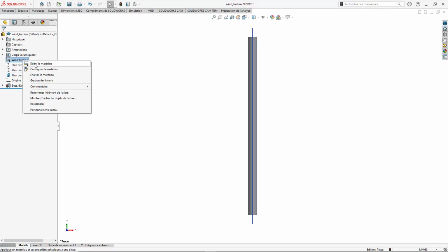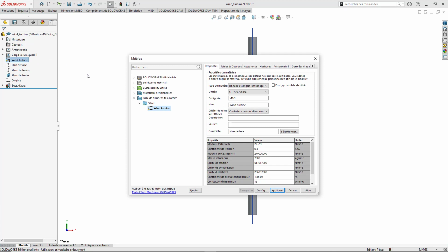We can also have a look at the parameters corresponding to the material that is used for the tower of the wind turbine. We can see that it's related to steel. Here we have indeed Young's modulus that we have used previously, and the density, right? But you can see here that there also is an additional parameter corresponding to the shear modulus G that I had introduced before. So indeed shear effects are taken into consideration.